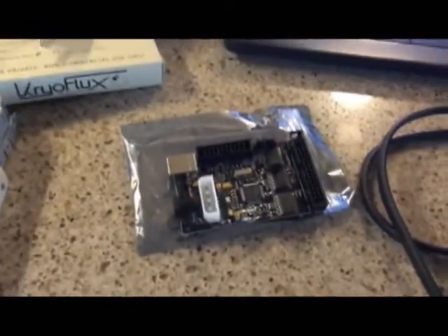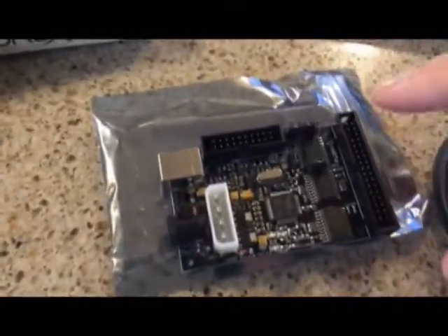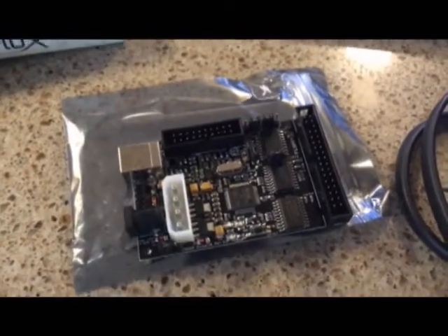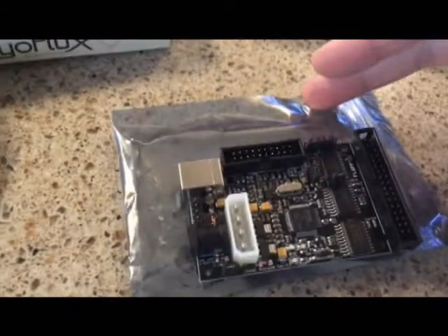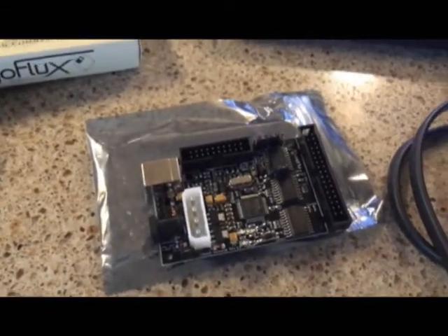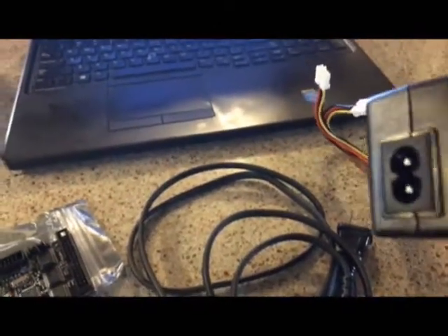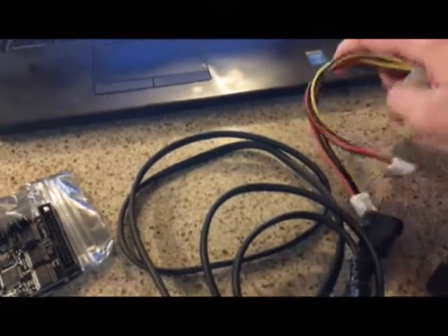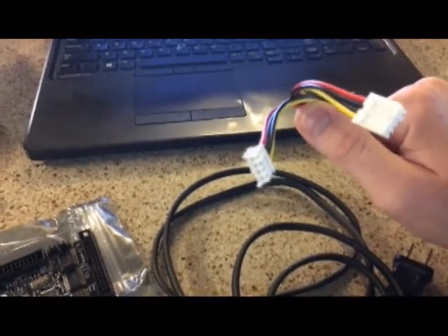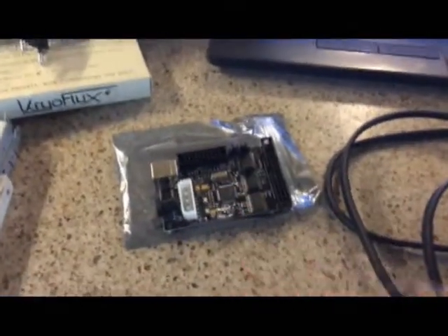Something else that you should be advised of is that the Kryoflux is a sensitive piece of equipment because it is an exposed board. It is at risk for being fried by electrostatic discharge. So it ships in an ESD safe bag, and some of the things about this aren't particularly straightforward. This plug-in that I mentioned earlier does not plug into the Kryoflux. This plug-in goes into your floppy disk drive. Do not try to use this power supply on your Kryoflux or you will ruin it.